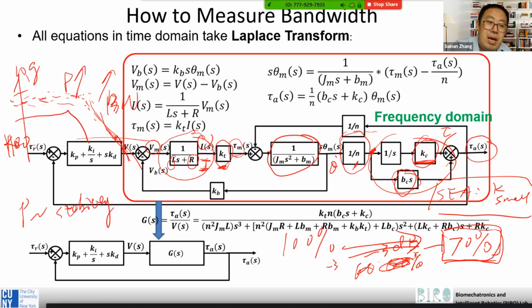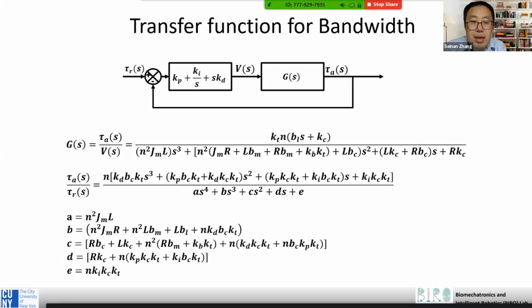Typically, if we lift it this way and you see a higher bandwidth, noise also has higher bandwidth. So this will transfer this kind of torque, but the system is also more vulnerable to disturbance. So we don't want the bandwidth to be too high. It's always a trade-off issue. So let's go to the next slide.